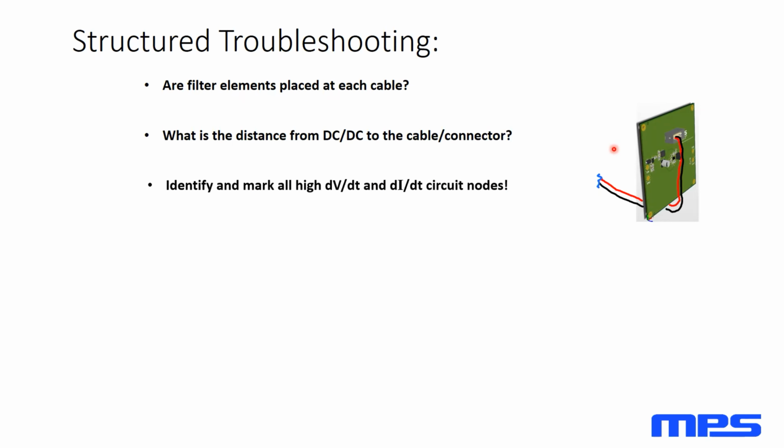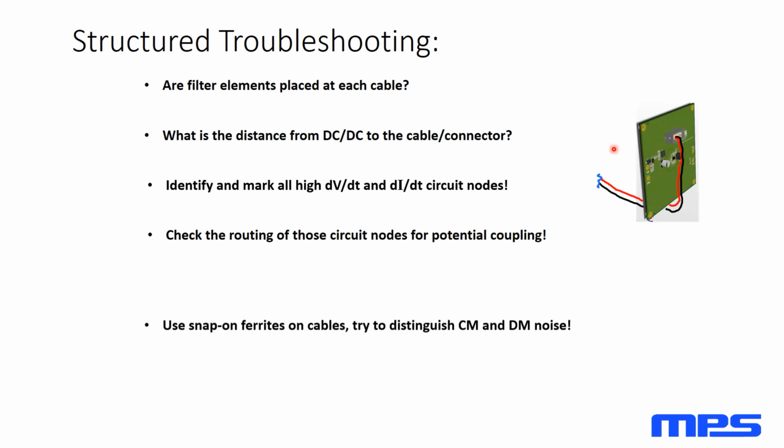Identify and mark all high dV/dt nodes and dI/dt nodes. I think we've taken a look at that in some of the previous presentations, but we'll take a look at some waveforms as well, just to reiterate that. Check the routing of all those circuits. Francesca's touched on that as well, and some ideas that we've had to maybe help with that or identify what are the best practices there. But obviously, these are critical things we need to look at.